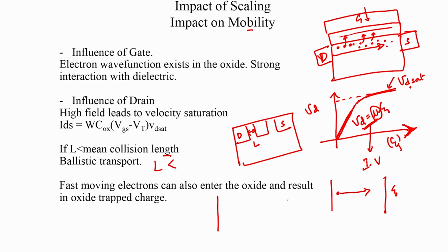But in a semiconductor lattice, the electron undergoes all these scattering events. It scatters with the lattice defects, with the lattice atoms, and you have electron scattering, etc. And therefore, because of all these scattering events, the electron experiences an effective drift velocity, and as the electric field is increased, this drift velocity saturates because the electron is still undergoing these scattering events.